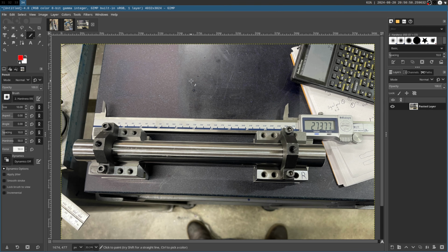So I set these two things down on the surface plate, put the bar in, and then clamp the bar in very, very lightly, because I can actually notice from these bolts being tightened that clamping this bar down, which is just so the bar literally doesn't slip out and fall on the floor, measurably affects the contact pattern between the points on the bottom and the top, right?